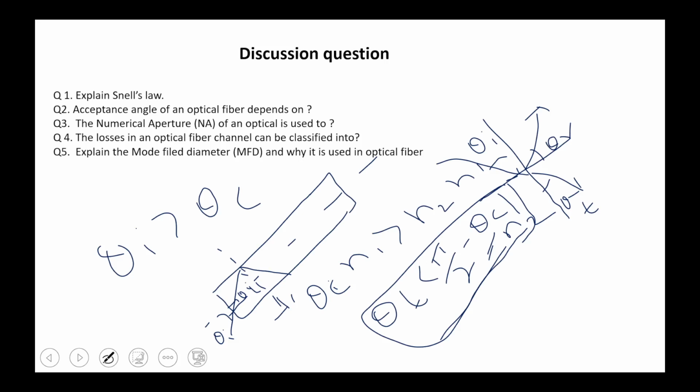So absorption losses are like that. OH is extrinsic, due to doping, and the SiO2 loss is intrinsic, because we have to live with SiO2 since that is what the glass fiber is made of. This is absorption basically because of the process.